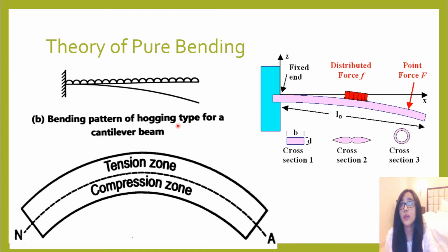Okay, hogging, और जो hogging moments आते हैं, bending moment, these are negative, right? तो जब भी आपने bending moment diagram for cantilever draw किया, तो every time when we were finding it, it was coming in negative. So these are negative bending moment, which is also called as a hogging. Okay, so the bending pattern of a cantilever beam is exactly opposite to that of a simply supported beam. सिंपली सपोर्टेड पे पॉजिटिव आ रहा था, सैगिंग आ रहा था ऐसे, राइट. अब ये कैंटिलीवर बीम पे हॉगिंग नेचर पे आ रहा है ऐसे. See, so it has become hogging nature here.